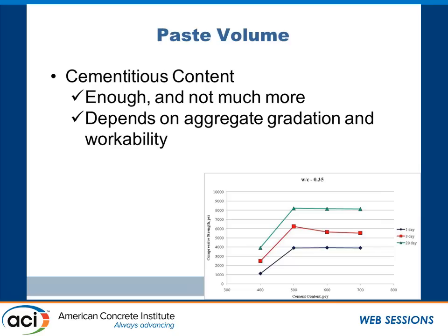All right, what we did is that we made mixtures with 400, 500, 600, 700 pounds per cubic yard of binder. We worked at fixed water-cement ratios, and we measured strength, permeability, workability. All right? And what we found, hey presto, if you haven't got enough paste in the system, you've got pervious concrete, and it doesn't hold together. Are we surprised? No. You get around about 500 pounds per cubic yard. For that same ugly red line aggregate system, we got reasonable strength.